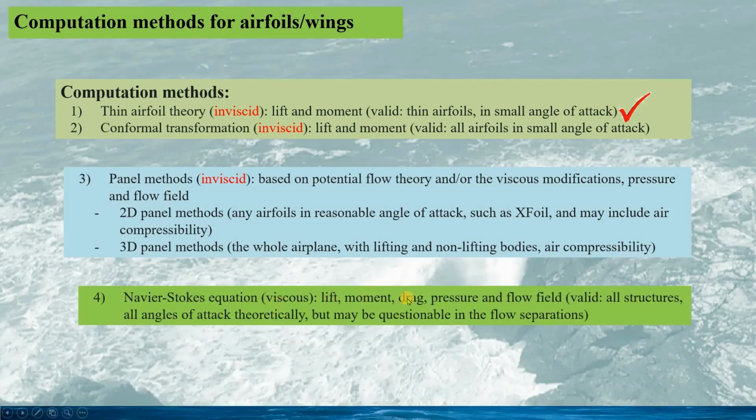The most complicated method would be the Navier-Stokes equation. This is the method for solving the Navier-Stokes equation for the viscous flow. Thus, the lift, moment, drag, pressure, and the flow field would be calculated. This method should be valid for all structures and all angles of attack in theory, but may be questionable in flow separations.